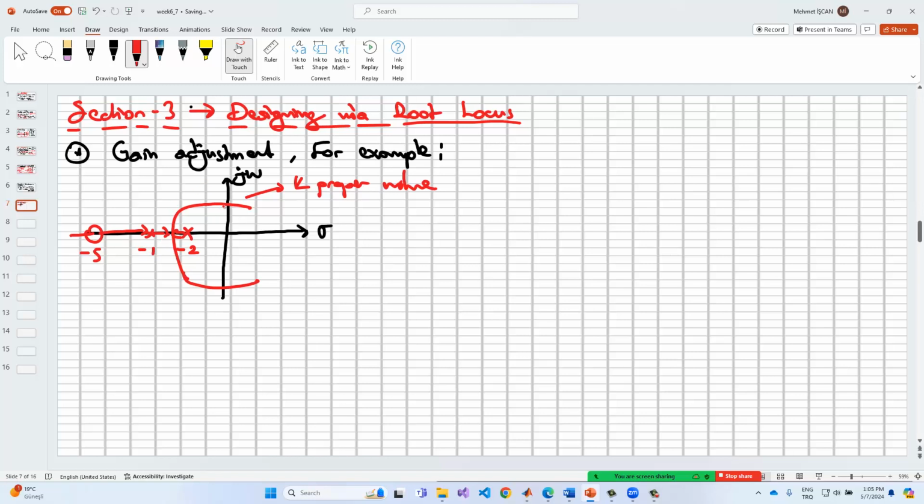But just remember that if we have the S-plane in here for a given system, then we can set the percentage overshoot and settling time along the red lines in here, because at each different K value we can draw these red lines. But these poles and zeros come from the open loop transfer function, right?